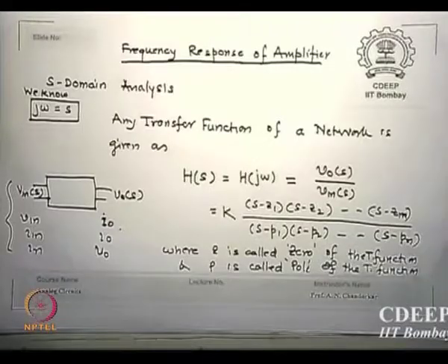Frequency response of amplifiers. Our assumption so far is that there is a frequency of signal which the device does not bother about, and it amplifies the output at the same frequency. Let's take an amplifier with an input signal at 20 kilohertz and a gain of say 100. So I know 1 millivolt at 20 kilohertz will become 100 millivolts at 20 kilohertz at the output.